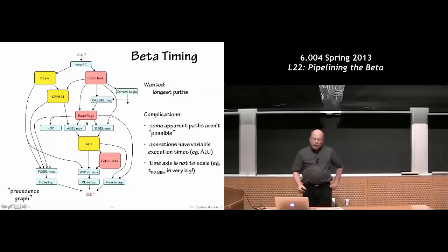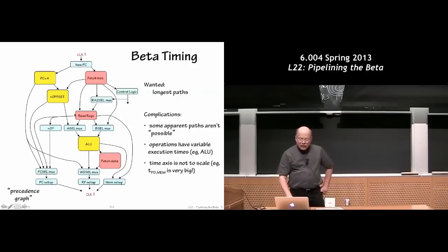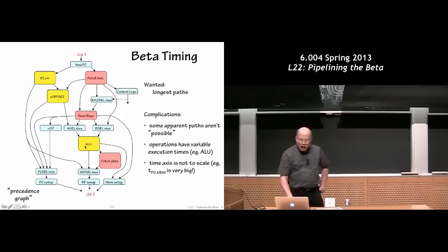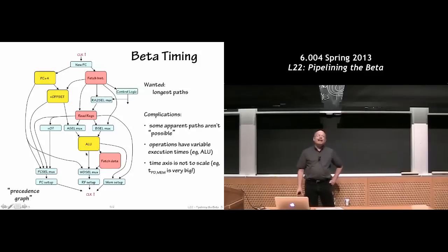The other blocks we want to think about are the big arithmetic blocks. So we actually have these big ripple carry adders, both to increment the PC, to perform the branch offset calculation, and to actually do arithmetic on data that the programmer is trying to manipulate.